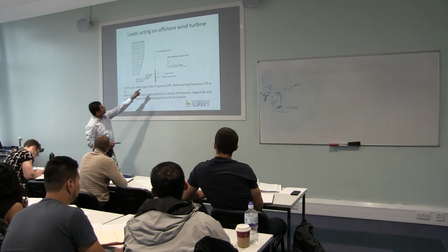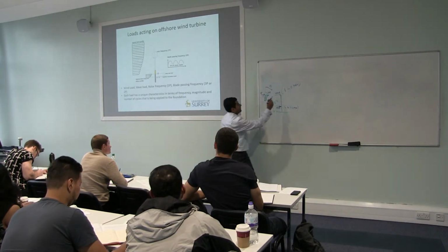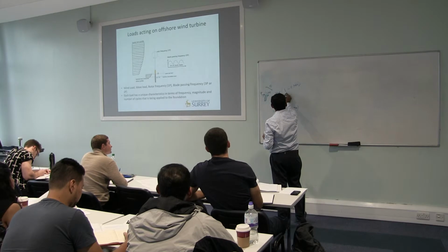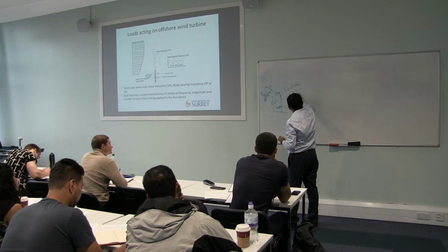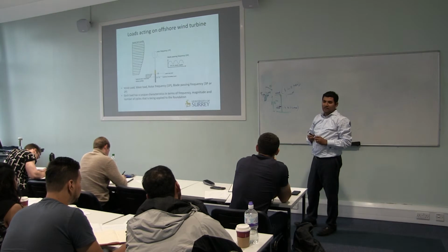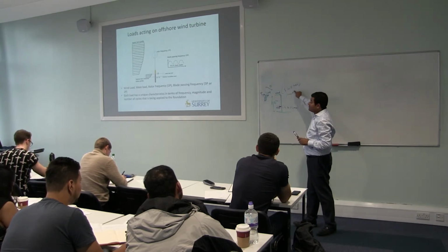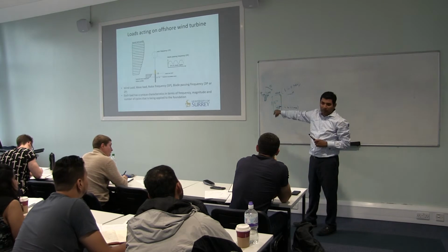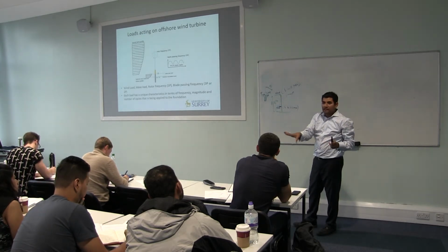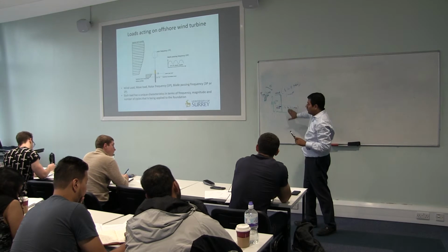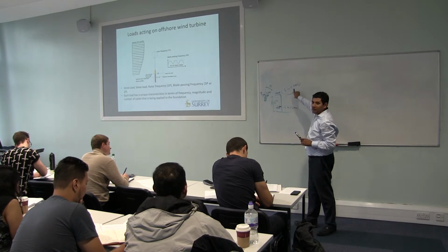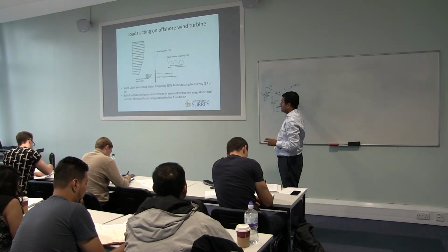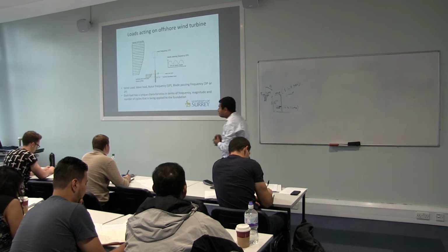That's the 1P load here. That load is acting here as well. So this load will be apart from the wind load, and also another one, this 1P loading. But this is in kilonewton range. Look at this. So we can ignore that in our calculation for moment. For our cases, we can ignore that. Wind and wave is adequate. Meganewton versus kilonewton, so quite the noise level. So you can ignore that.